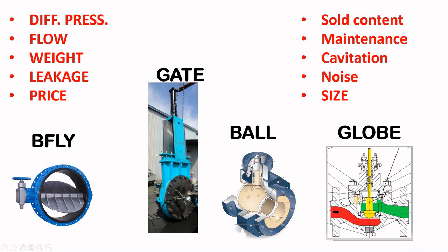Cavitation, again: some valves are more prone to cavitation than the rest. We will have other videos discussing cavitation and the sizing itself. What we know now is that some of them have anti-cavitation or are less prone or susceptible to cavitation than others. Again, for noise, some of them give you a good solution for high noise applications and will reduce the noise to an acceptable level.